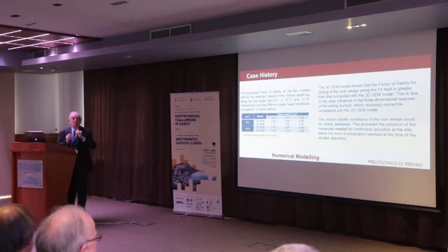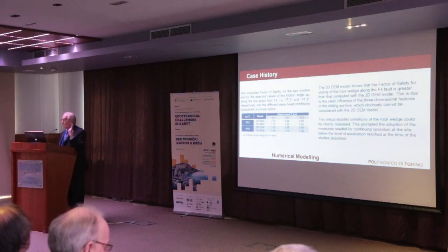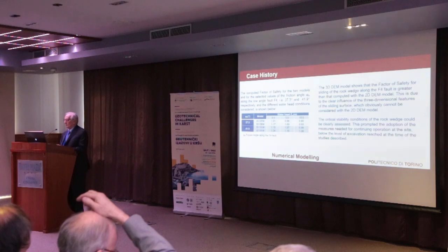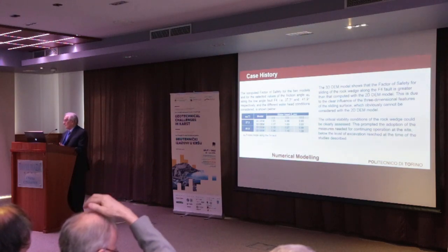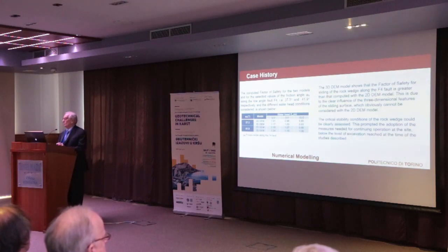We can assess what is the continuity? Are there along that surface some rock bridges? Is the continuity 80%, 100%? Of course, we have estimated it. Don't forget that there was an instability at the top. You remember that I showed that to you? And of course, you study that very carefully. Anyhow, you need to give an answer to somebody that is asking you a question. You say, oh yes, I am in critical conditions. I can tell you what are the measures that you need to adopt in order to continue the operation safely.